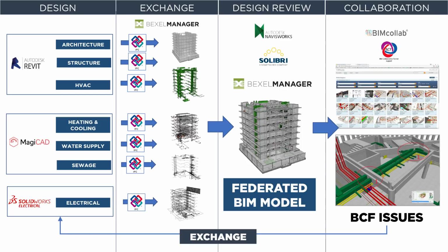When we merge all of them together in one project, we get a federated BIM model, and IFC files become sources or source files inside of that federated BIM model. Design review and clash detection is usually performed on the federated BIM model, where conflicts between different disciplines can be visible. The project manager can now easily spot mistakes and inconsistencies between different disciplines, and he can submit them back to the corresponding engineers for revision.